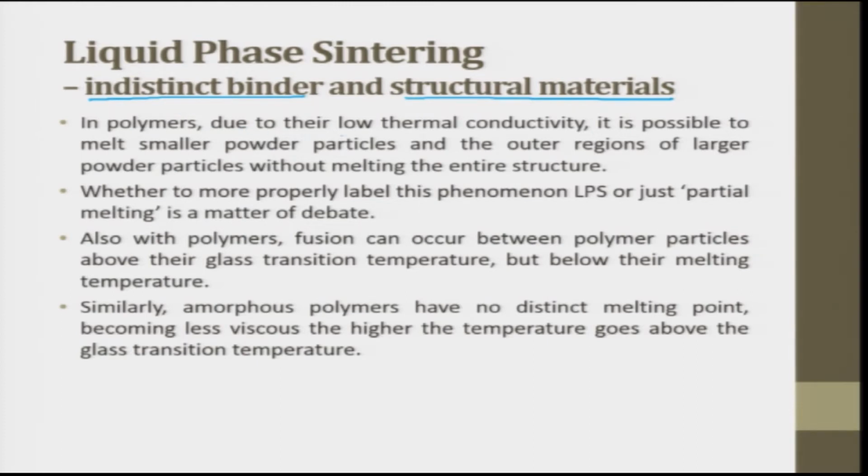In polymers, due to their low thermal conductivity, it does not absorb heat, so it is possible to melt smaller powder particles and the outer region of larger powder particles without melting the entire structure. That is nothing but the distinct binder and structural material. Whether to more properly label this phenomenon as LPS or just partial melting is a matter of debate.